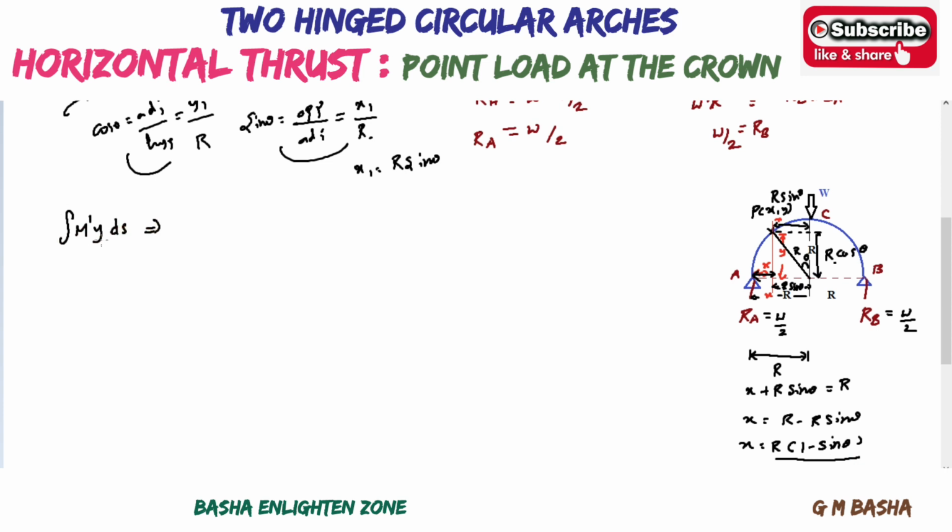So what is y? This y will be equal to r cos theta. And what about this ds? ds is the small elemental part, take it directly as r d theta. So please remember this one: in circular arcs you will always get ds as r d theta. And what about this m dash? For m dash, resolving this force, it will be equal to Ra into x. Okay, so that is the moment here. So what is Ra? Ra will be equal to w by 2, and the x distance will be equal to r into 1 minus sin theta.